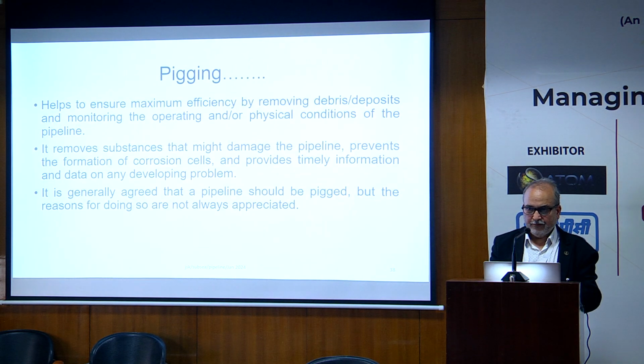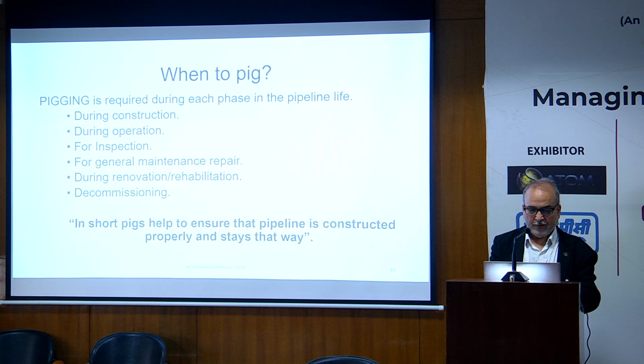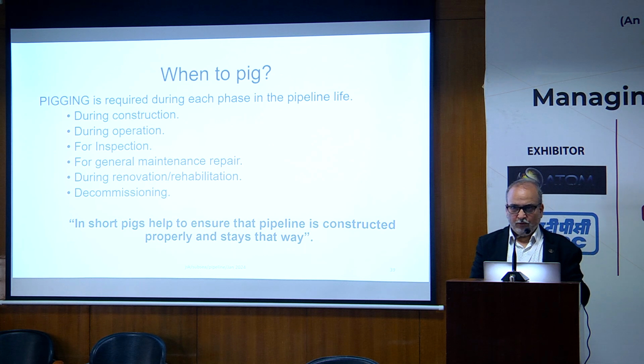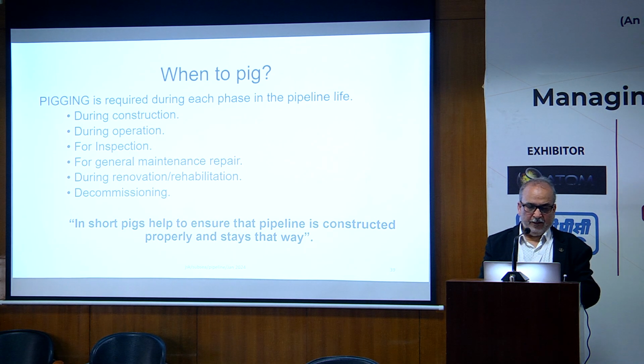Normally pigging helps the way it helps for onshore pipelines: it helps us to know the health of the pipeline by analyzing the debris or deposits recovered from the pipelines. Pigging, as we understand, is to be carried out throughout the life cycle of a pipeline, right from the construction phase to the decommissioning phase.